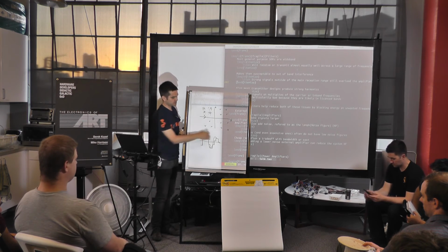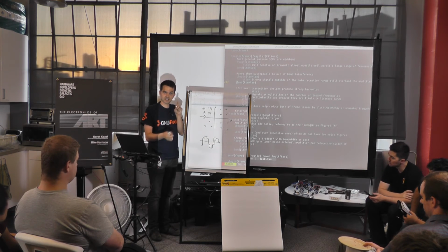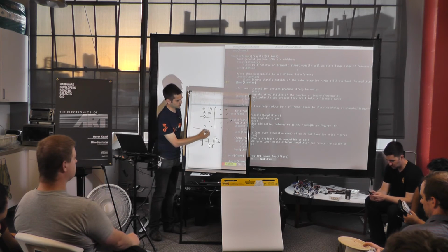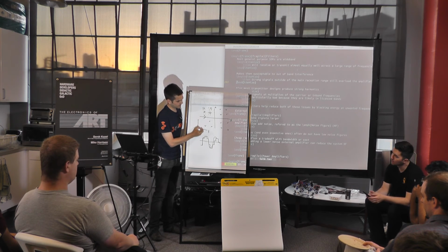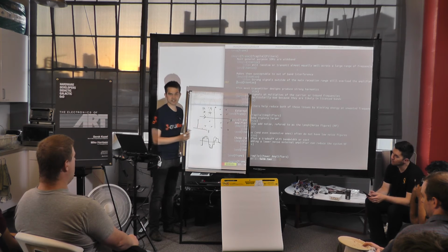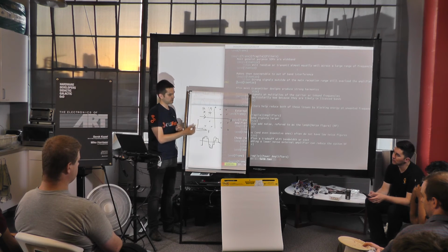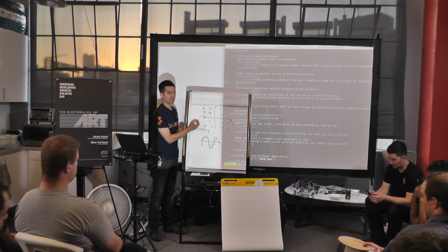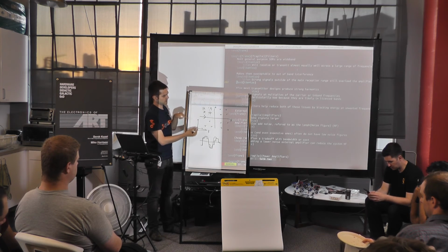All right. So this is quantization noise, and the other thing that the resolution of the ADC limits you at is if you have a signal, so this is over frequency now, and you have a very, very strong signal here, and then you have a tiny little signal right next to it, or somewhere within the range that you're looking at. So we're looking at this range here. If your ADC isn't high enough resolution, you don't have dynamic range, the ability to both resolve a little signal here and a strong signal. And so that dynamic range can be helped out.